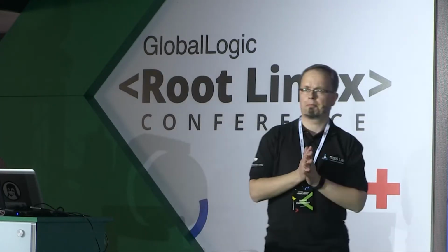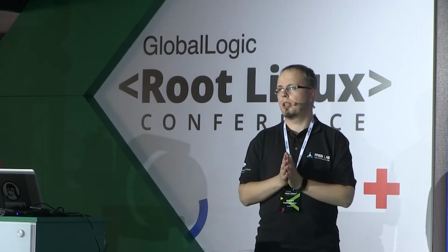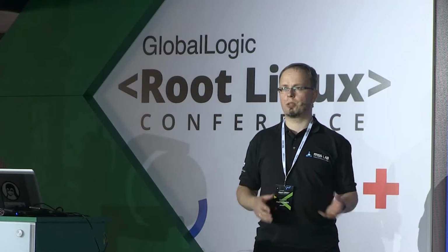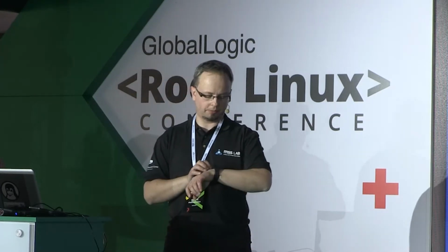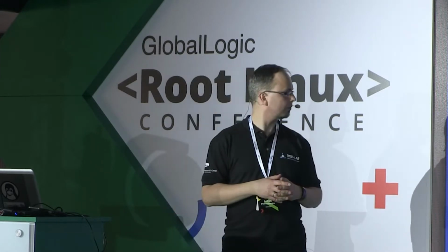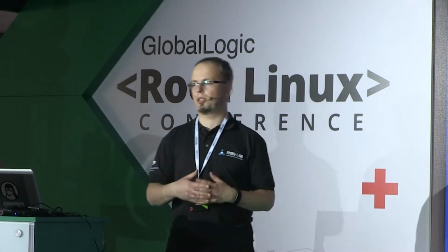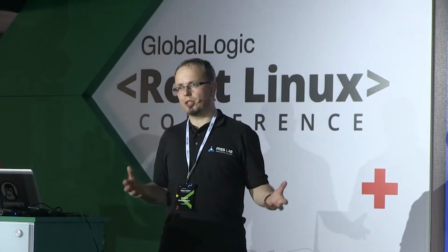So the design is like this. We will implement a loopback function, which will retransmit to the host whatever it receives, converting the small letters to capital letters. The gadget will be composed with config.fs, and it will be composed of one function and one configuration. The actual function will be implemented as a shell script with function.fs, and we will ignore EP0 events, which is a bad design, but we are fine with that for this demo.